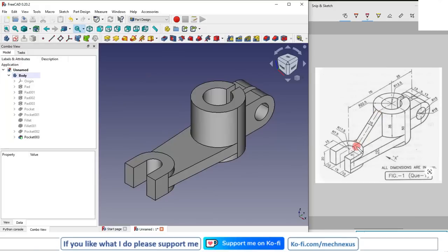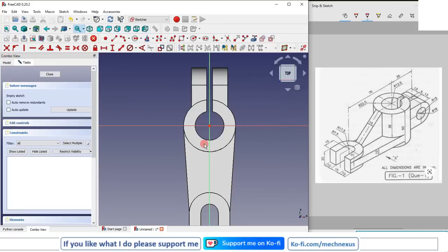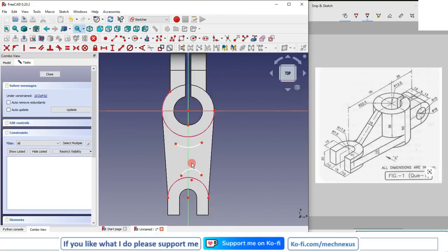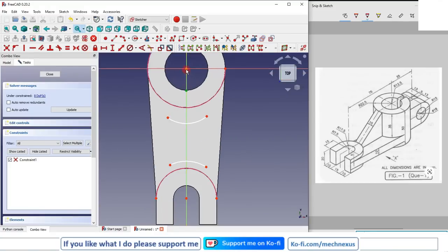Now we will make this rib. So for this I will select the face and create a sketch. This rib is of 10 mm thickness. So I will click on project geometry. I will project this and this, and I will draw the 3-point arc at this side and one 3-point arc on this side, and I will merge the center. Similarly I will merge the center here, and I will join these two with a line.